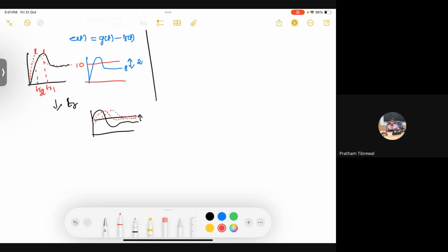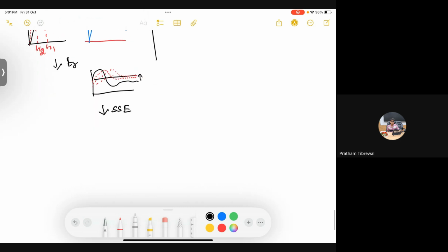Sometimes there is a disadvantage. As there is an advantage, there might be a disadvantage also. It may go beyond the limit. For that, we will use different actions. Next, different integral or control actions. Seeing from the proportional control point of view, it will try to bring the steady state error closer to zero, so it is reducing the steady state error. The problem is whenever the error is very large, it tends to increase the oscillations or reduce stability. That's what I explained last time.